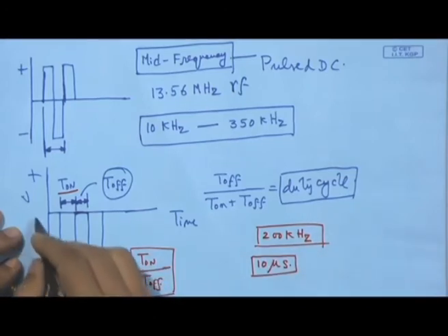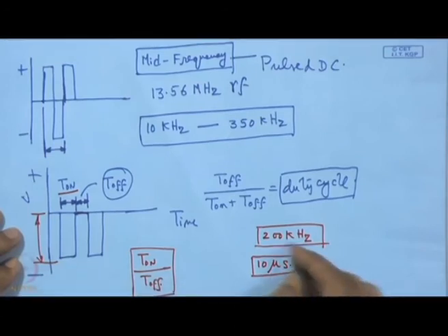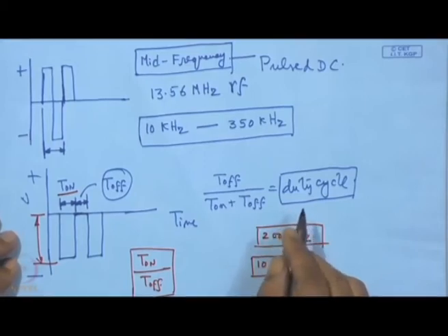This also depends upon this impressed voltage. So, based on experience, one can decide what should be the duty cycle, but at the same time one should not ignore the productivity. One thing in the whole process is to protect the target and not to arrive at a situation that is very damaging, that means arc discharge, which should be avoided anyway.